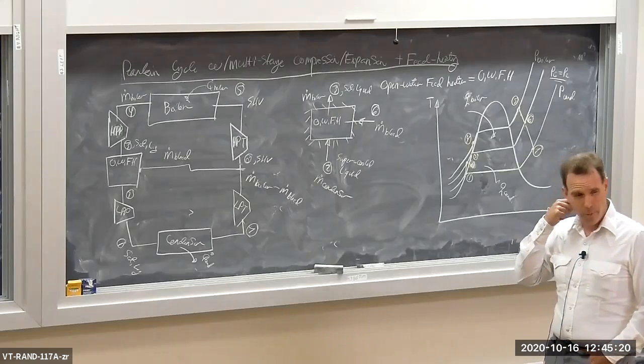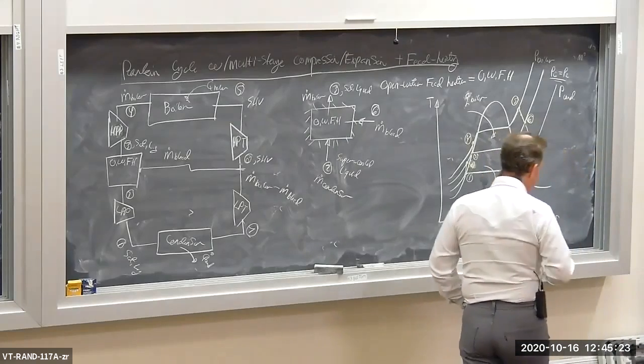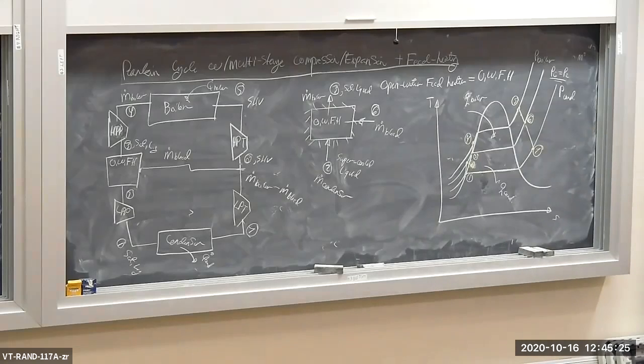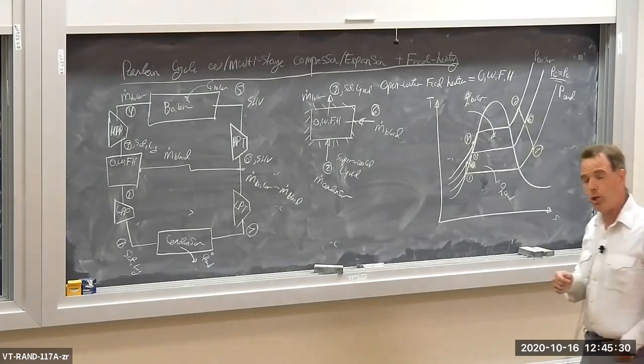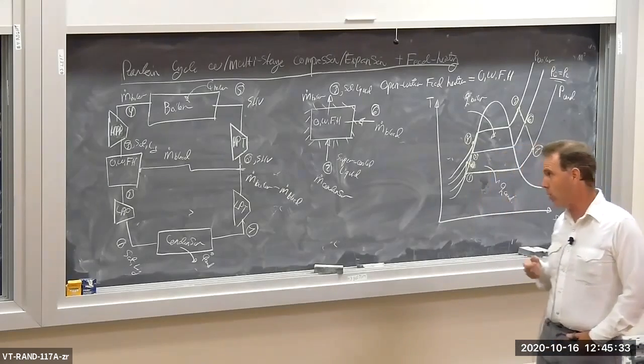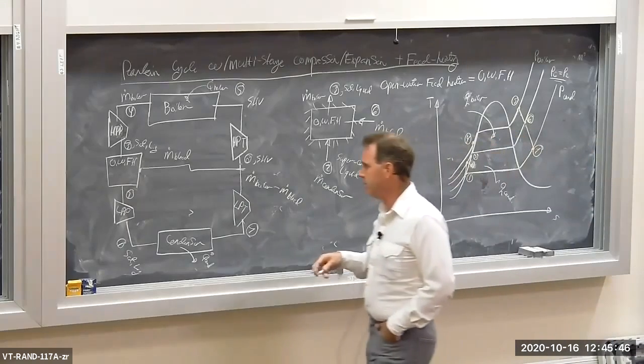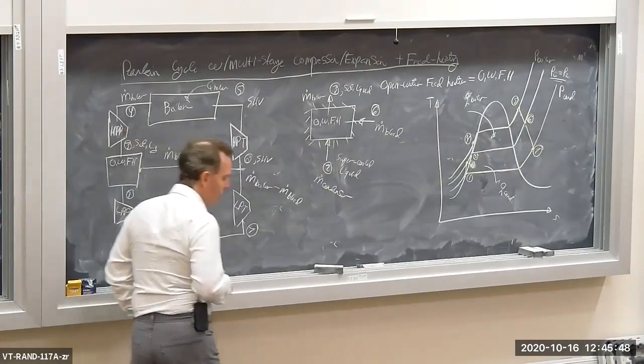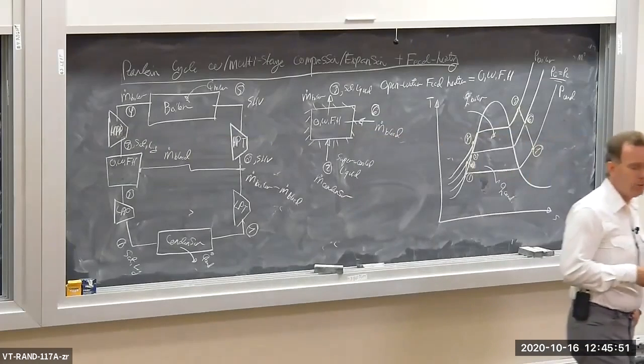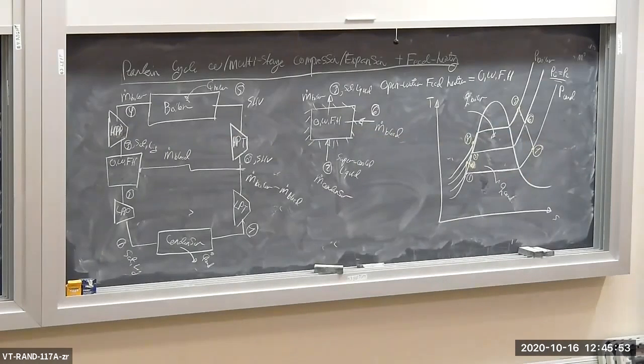As I recall, without regeneration, thermal efficiency was about 25%, and with a regenerator efficiency of about 80%, the thermal efficiency of the Brayton power plant gas turbine went up to like 46%. With these open water feed heaters here, you're lucky to get a 1, 2, maybe a 3% increase in efficiency of your overall Rankine cycle.